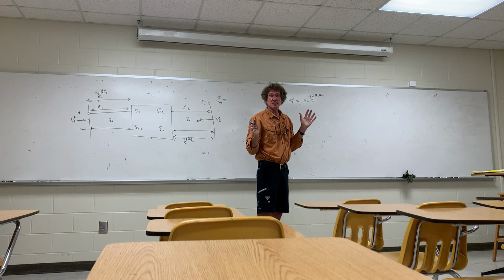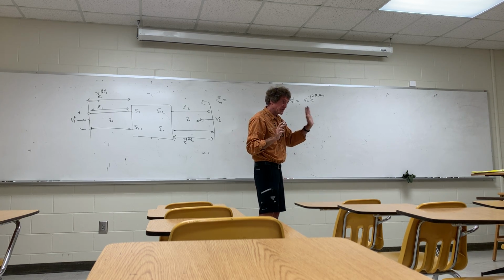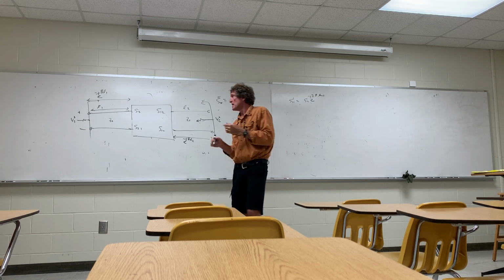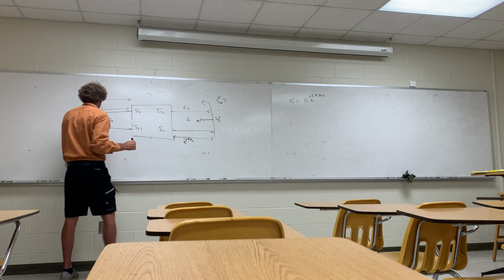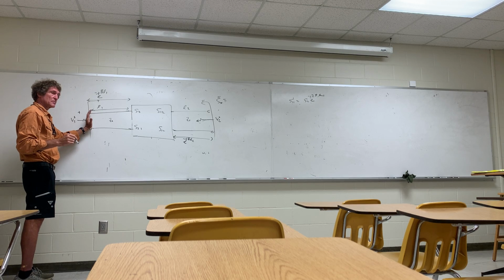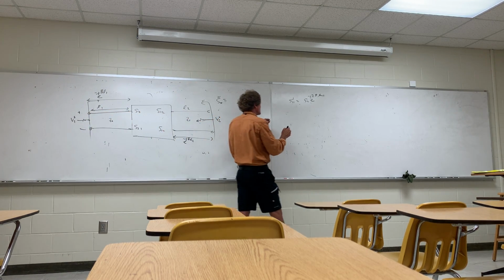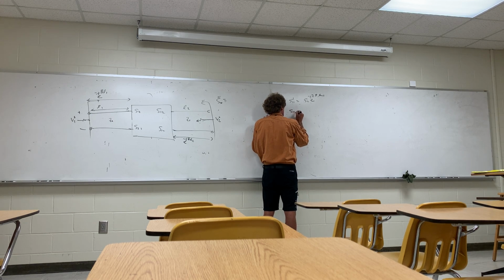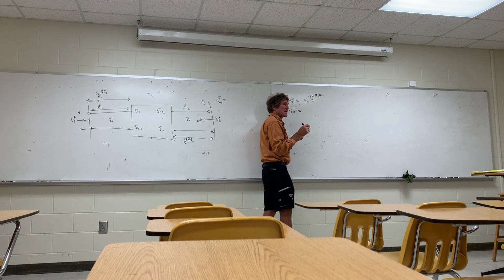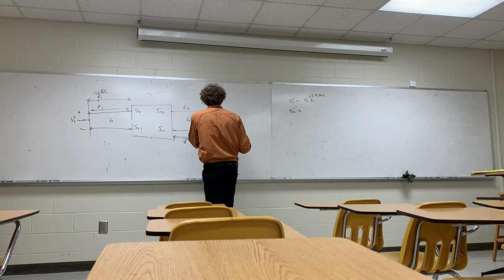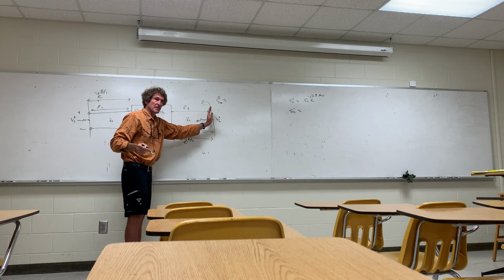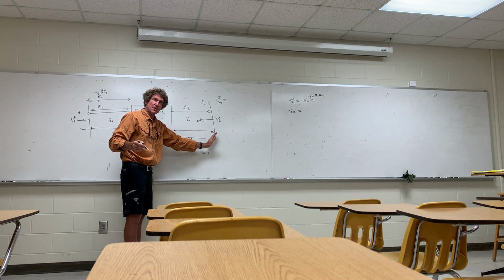I mean, do you all get this? It's just one of these things where there's phase delay now, because I'm getting the S parameters for this system at these ports right here, with the shifted reference point. What do you think happens to S22? Well, same thing as S11, right? Here, I send in my V2 at this port right here. This is a shifted reference plane.